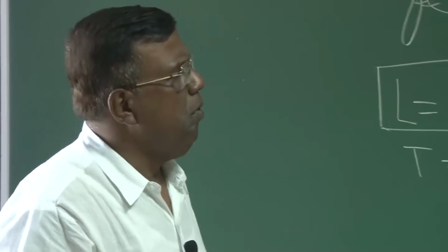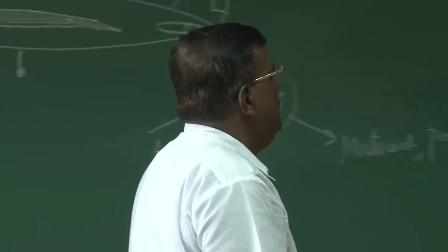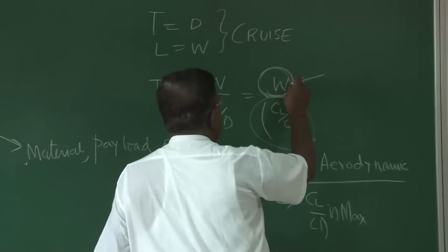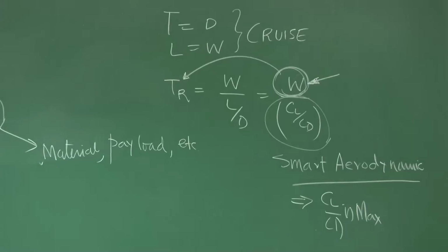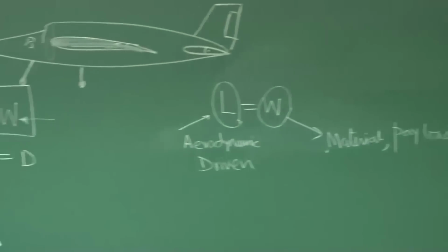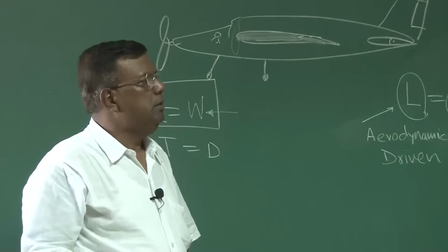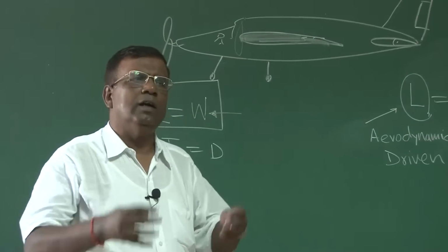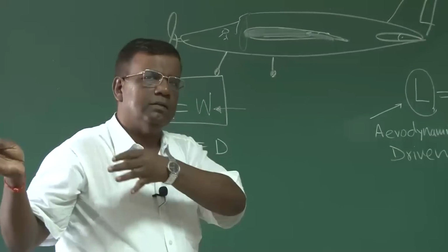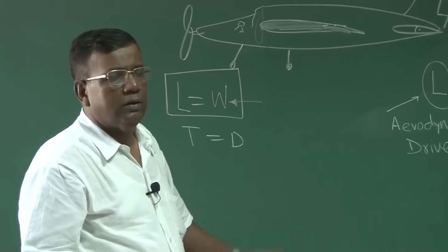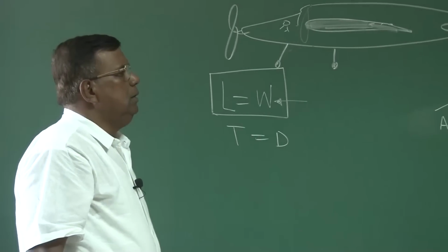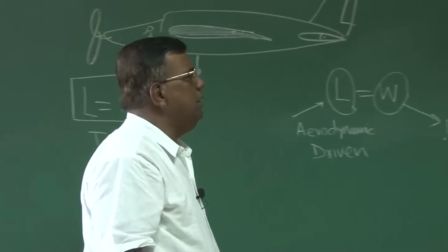So I need to know this weight, because that will tell me what the thrust required is, and I can now think of what sort of an engine I will be picking up, right? Also remember, I have told you the engine part will be almost like we are taking things from the shelves, right? Standalone engines are available. We are not going to design an engine in this course at all. So weight is extremely important that way.